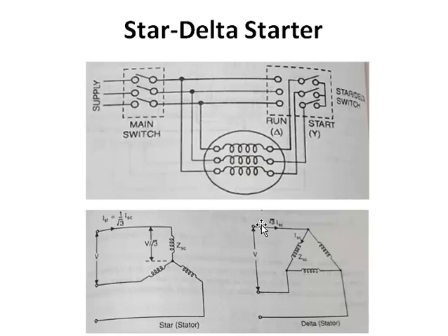So during starting of the machine, it is thrown onto the star, which makes a star connection, and when it is running, it is put onto the delta. Why is it put onto delta? When the motor starts running, it has to take the full load, so we need to apply the full voltage. Now when it is in the delta, the full voltage is applied across each winding.